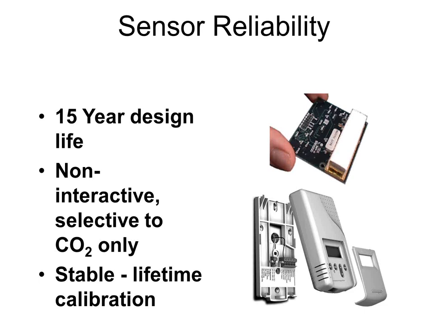The other thing that's been really nice is I don't have to calibrate CO2 sensors anymore. I spent a good portion of the early 2000s calibrating CO2 sensors every year, and that was a pain in the you-know-what. Going up to each sensor, hooking up a can of gas to it, running the gas through there, pushing the button at the right time, hoping I zeroed it out the right way. Then I'd have to worry about somebody else coming along and pushing the button with no can of gas connected to it, and they messed up my reading. The good news is all that's gone away.